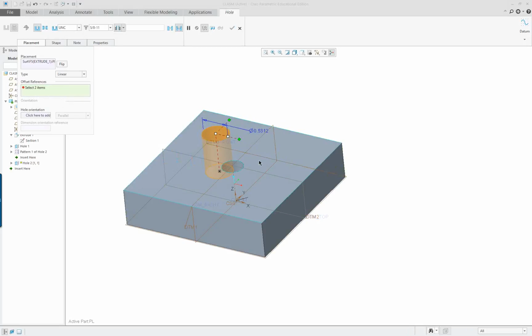Now you can try dragging these over, and that's why putting these datum tags a little bit away from each other is helpful. So for instance, I did move this datum plane, so it's very easy for me to go here rather than pick up the wrong one. Now on the other one, I did not move it. So you can see it doesn't know what to pick up. I want to pick up the one underneath it, and I didn't. I picked up the assembly.